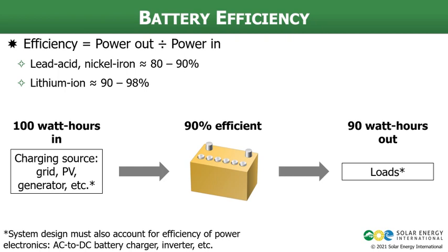That's going to affect the power. Amps times volts equals watts. So you're going to have lower power at the lower voltage. So we need to take that into consideration when we're calculating our efficiency. That's very important. So it's important to know, how is the battery manufacturer rating their efficiency? Are they doing it based on amps only? Are they doing it based on power? Are they doing it based on energy? It's going to make a difference, and we need to be able to make sure that we're comparing batteries using the same metrics.